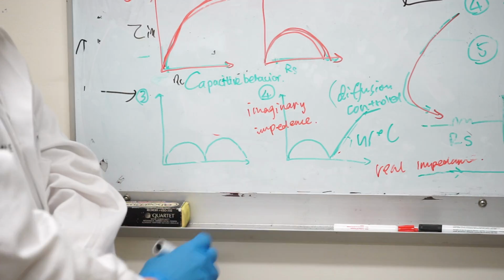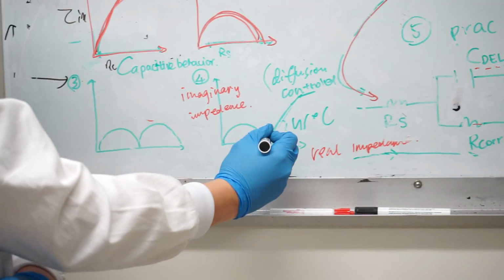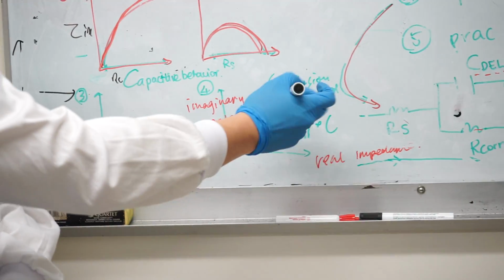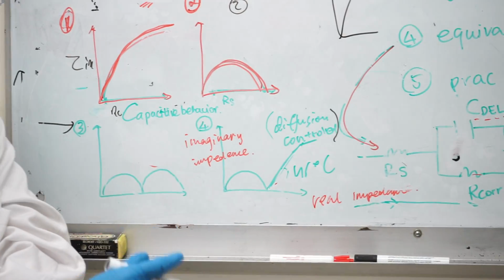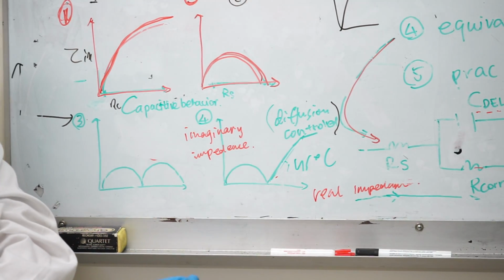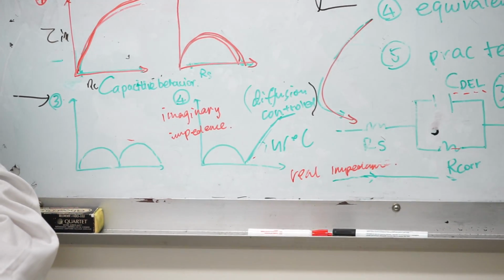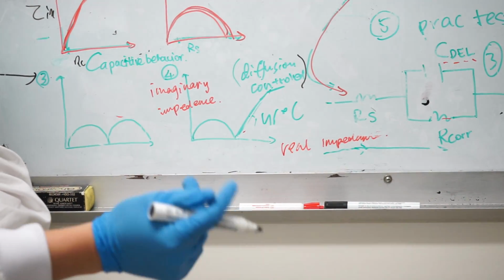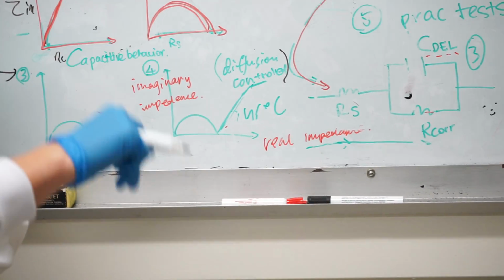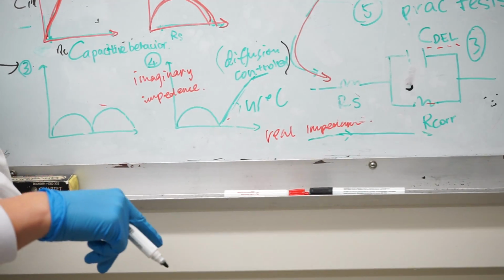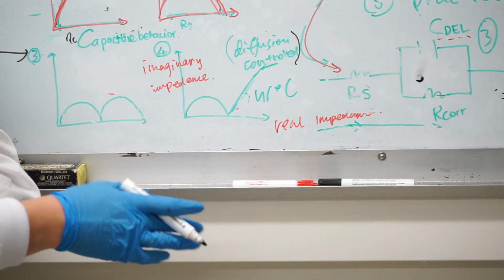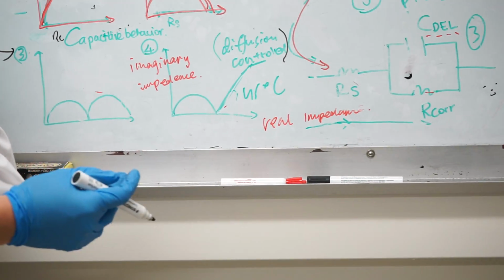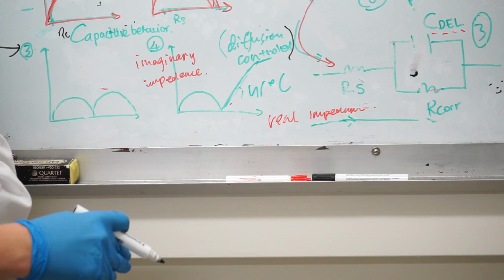This one here is a case where you have one semicircle and a 45-degree angle going up. That represents diffusion control, meaning that even though your sample is exposed, there's a diffusion control mechanism taking place, which means that the ions have trouble getting to the reaction site. It needs some time to diffuse. It could be time, or the temperature, or maybe agitating your solution. It depends, or it may even not corrode because ions cannot get there.